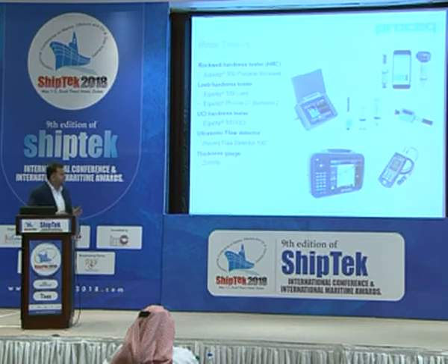Just to give a quick view on different testing, for example, on portable hardness testers, we have the Rockwell hardness tester, which is basically the same as the stationary hardness tester, based on the indentation method. And we have the Leeb hardness tester, the dynamic hardness tester, the world's first portable hardness tester, which was invented about 40 years ago in Switzerland. And UCI, the ultrasonic contact impedance technique, for portable metal hardness testing.